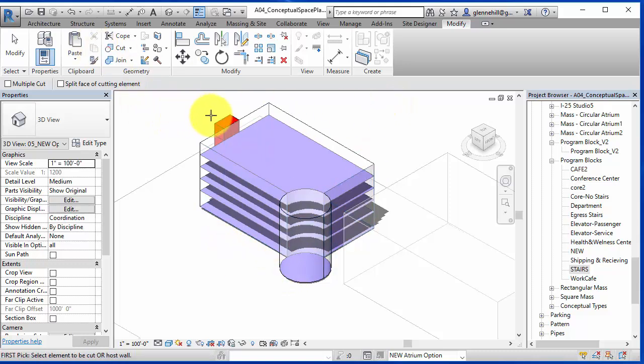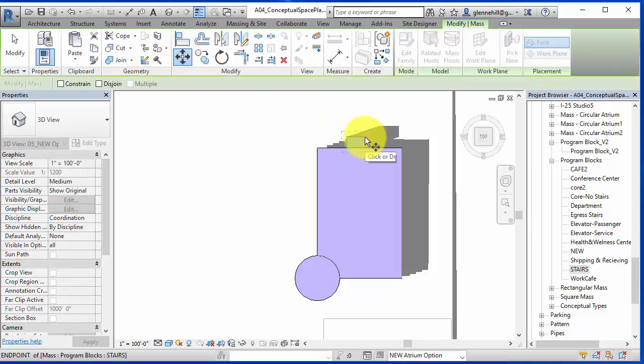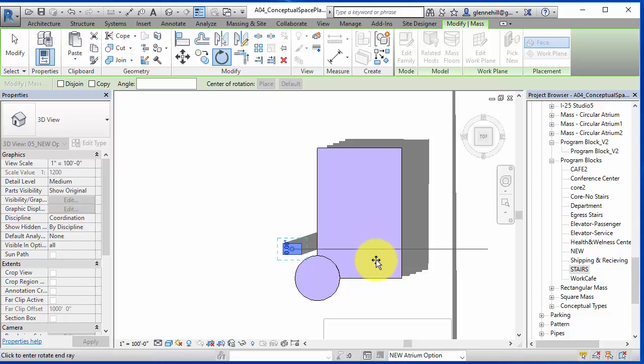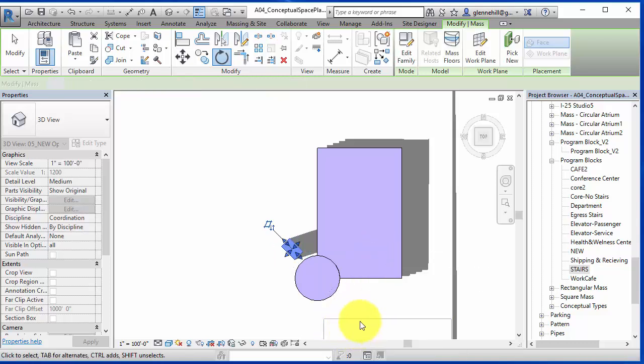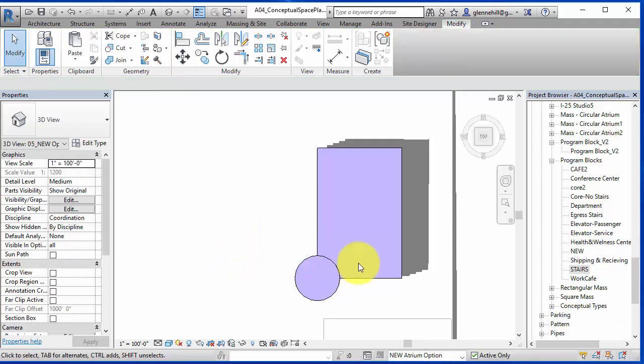And so let's create another stair over there. So I'm going to go over to the view here and do a move. So we'll go here, here, and I'm going to move that over to here, but I want it right here diagonally at 45 degrees. So I'm going to rotate this 45 degrees and then move it into place. And of course it gave me an error statement there because this has now been moved in here, but it's not cut from it, and that's what I need to do.